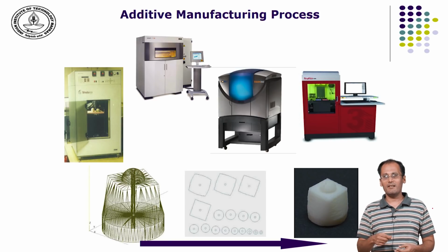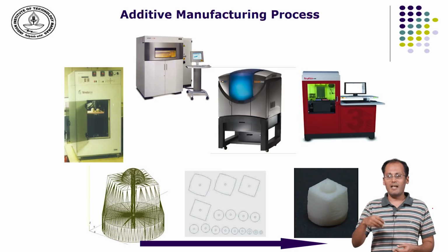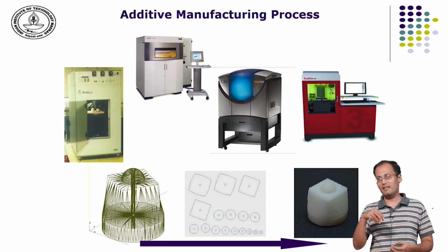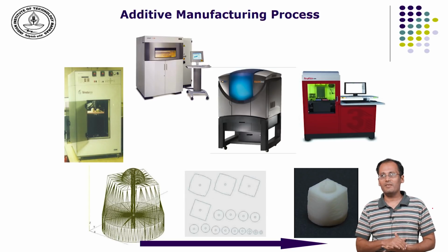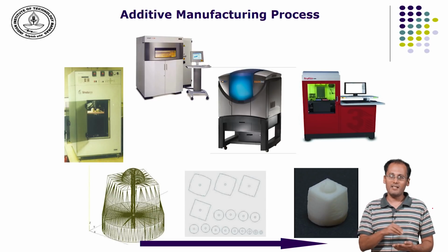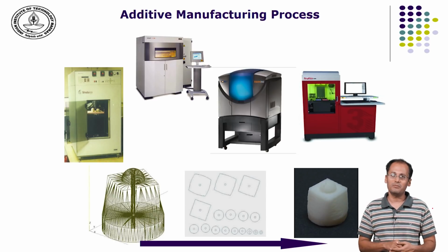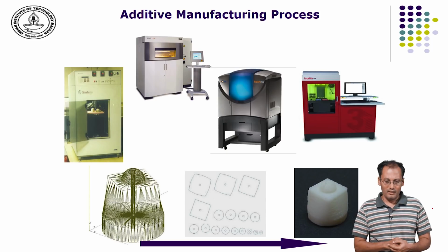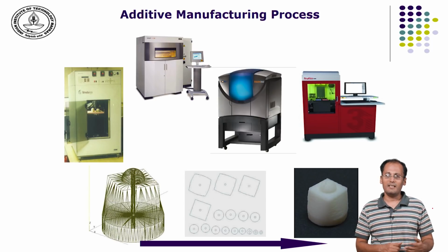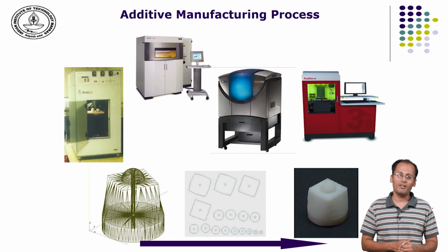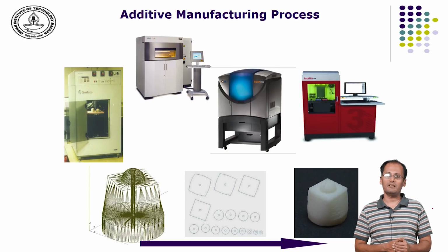We have a confocal laser, and we have powders being deposited using nozzles. The composition of these powders can be varied as the nozzle moves on the table to print the part. In similar fashion, in other technologies as well, one can think of heterogeneous part fabrication or functionally graded parts.